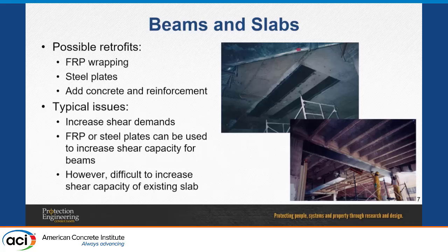But now, how do you do that for slabs? So that's very challenging, or I would say not practical, right? So for slabs, it gets tricky. And you have to see whether even that retrofit will work at all or not. Again, I'm saying not necessarily whether it would work for flexure. It may work for flexure, but whether it may work for shear, the original capacity of that member.